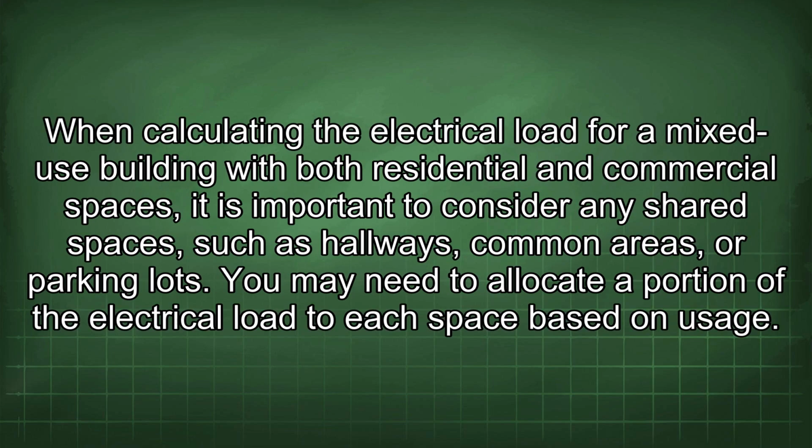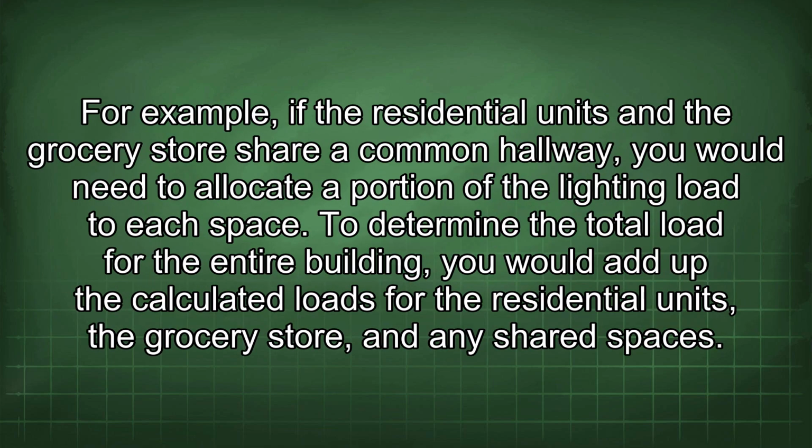When calculating the electrical load for a mixed-use building with both residential and commercial spaces, it is important to consider any shared spaces, such as hallways, common areas, or parking lots. You may need to allocate a portion of the electrical load to each space based on usage. For example, if the residential units and the grocery store share a common hallway, you would need to allocate a portion of the lighting load to each space. To determine the total load for the entire building, you would add up the calculated loads for the residential unit, the grocery store, and any shared spaces.